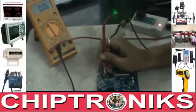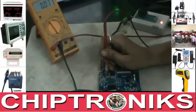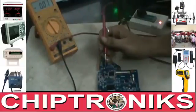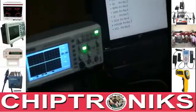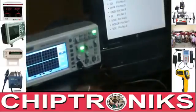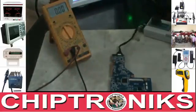If you check, look over here, there is no data. Here I'll check pin number 6: no voltage, and clock. Here I'll check pin number 5. Yes, there is voltage, but we are not sure whether the clock is coming or not. So that's why we need an oscilloscope. And here we check pin number 2 also, the signal output pin. This is pin number 2. Here I get 3.3 volts on pin number 2. But we are not sure whether this BIOS is working or not, or whether the inside file is fine or not. So we need an oscilloscope. I'll show you how to check.